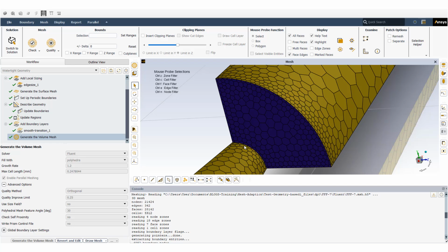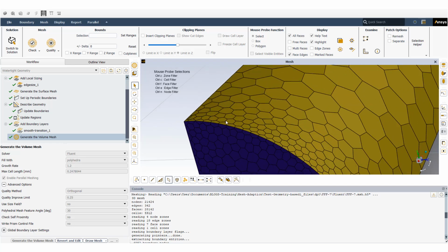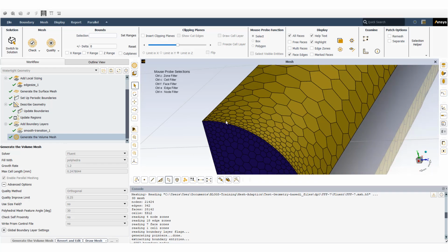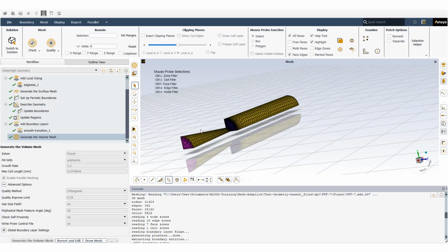This is the mesh on the curved part at the sharp corners. We already learned that if it is only 5 or 6 cells, it is a coarse mesh. But this one is, I think, 9 or 10. And also here you can see the good mesh. But again, the total number of cells is just less than 6000 as I had before.